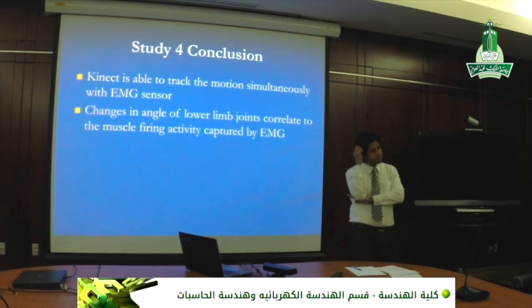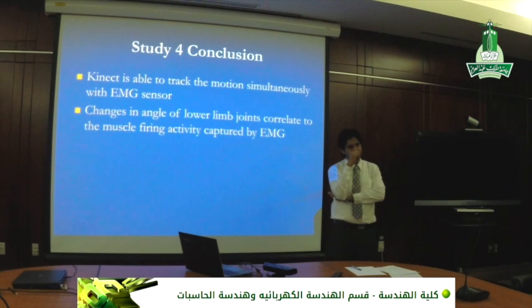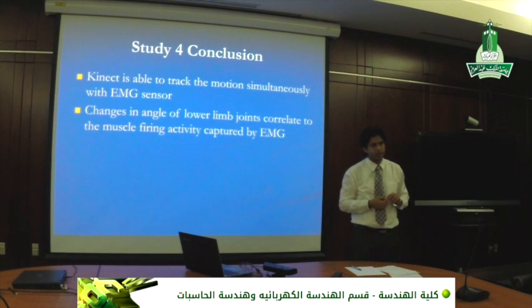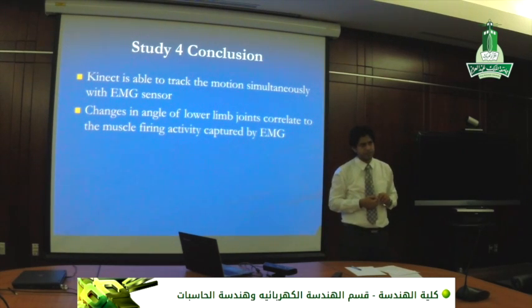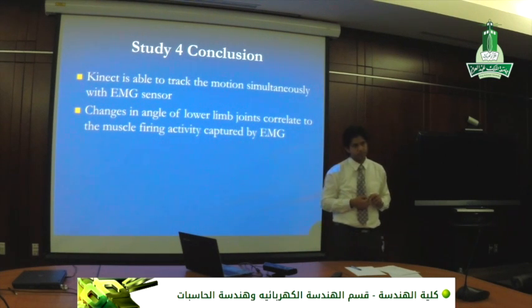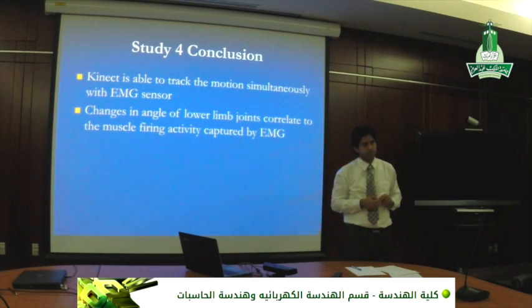Now, once they are inertial sensors, are they giving you the absolute values? Because my understanding is that most inertial sensors are rate sensors. That's why you can see peaks in all of your plots, only in the case of these inertial sensors.